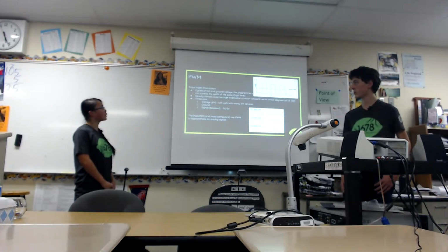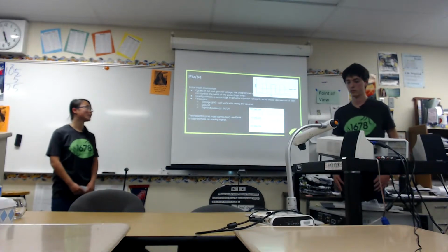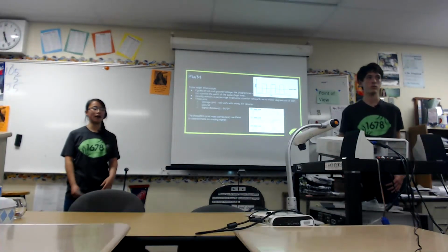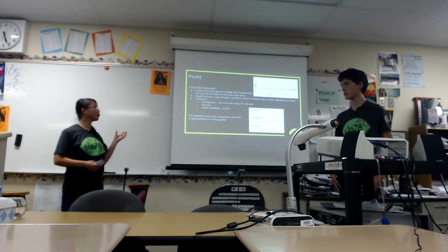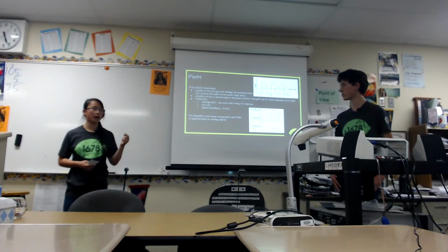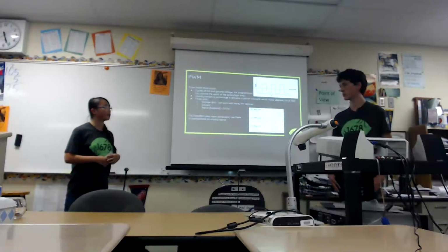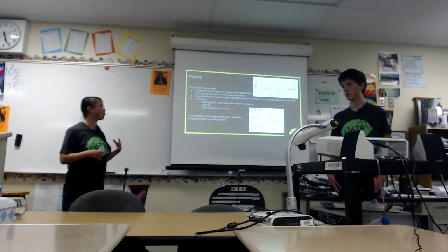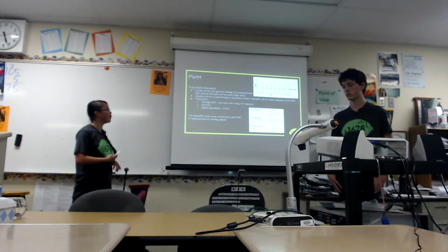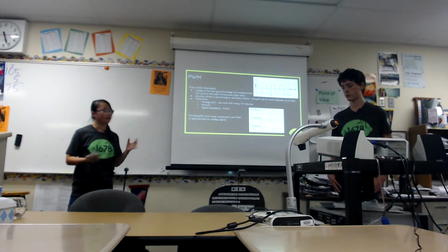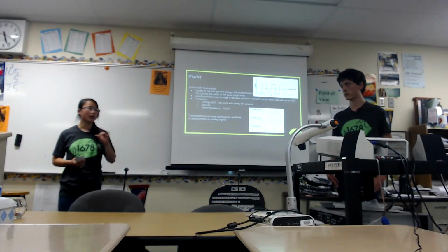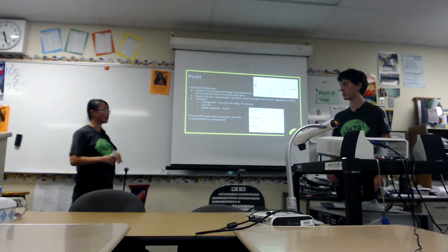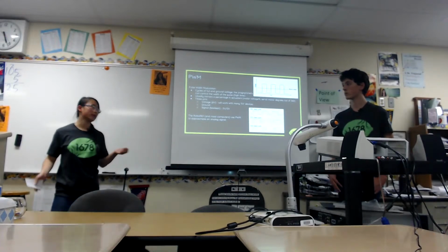And then there's PWM, pulse width modulation, and it has different cycles, full and no power. It's called the duty cycle, the percent of time that it's at full power. So that can be used to simulate an analog output. For example, if you have a motor and you give it full power half of the time, then that's as if you're giving it half power the whole time.